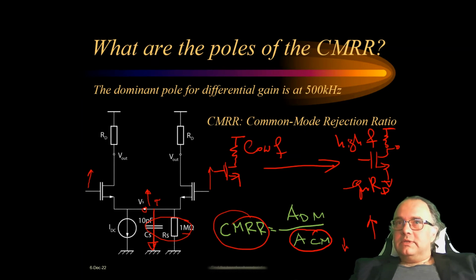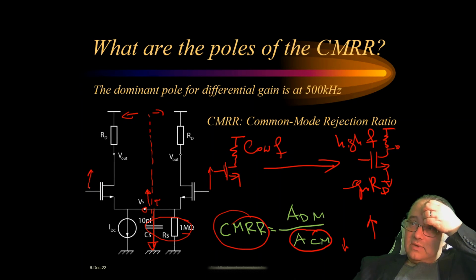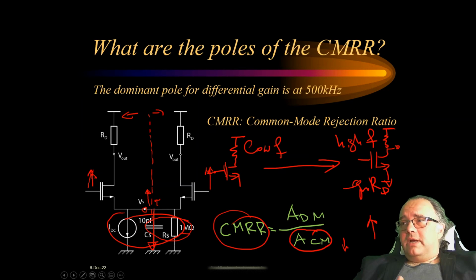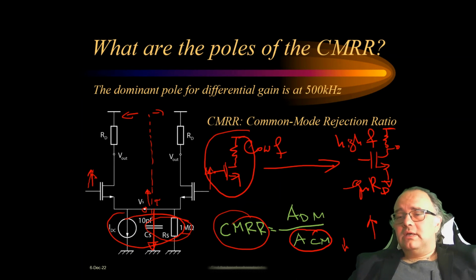We know that it is fully symmetrical. You see here that this circuit is symmetrical, what is on this side is exactly the same as this side. For common mode signals, this changes in the same way as this changes. And then the common part can be split simply by 2, and we'll have a circuit of this type, which we can easily analyze. This is done in the next slide.